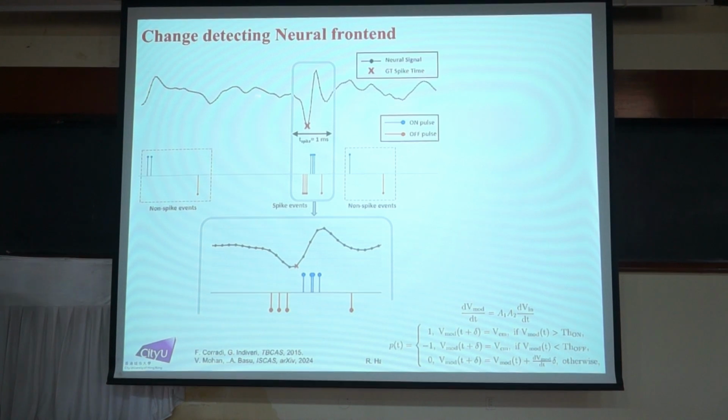There are some other noise elements that are also triggering pulses, right? So it's not entirely true that only the action potential is going to give you pulses. But if you can play some tricks, choose your thresholds in a good way, or maybe even do adaptive thresholding, you can reduce the amount of these spurious spikes and potentially just have pulses being generated for this part.